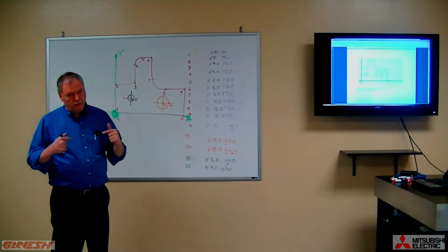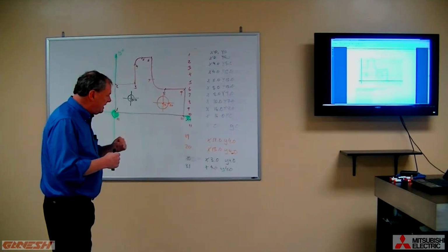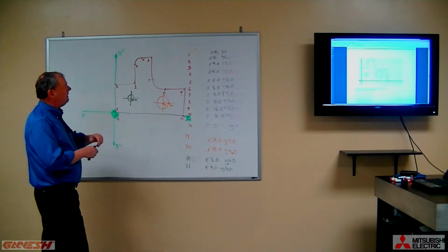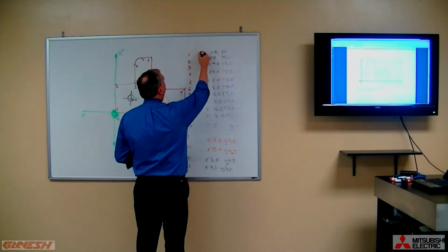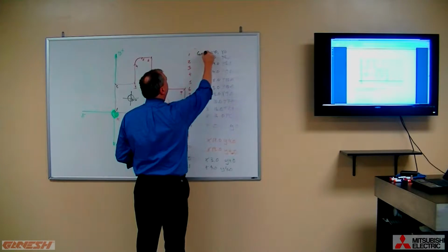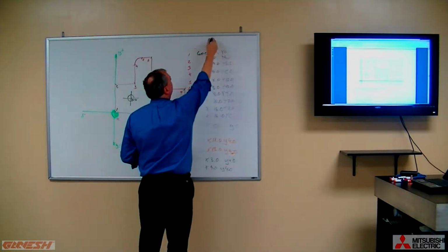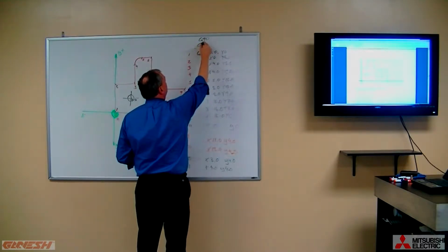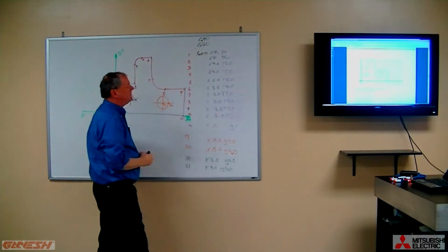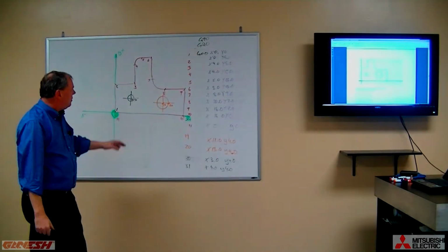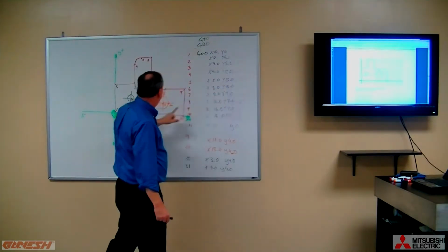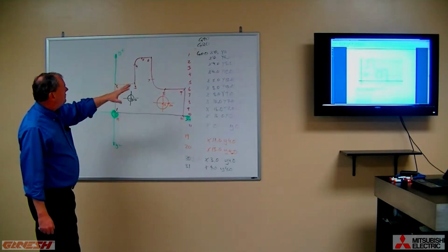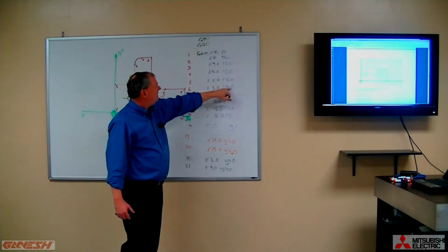Based on what we've talked about so far, I imagine you would want to make our first move a rapid move to x0, y0. So we'll go G00 here, and there's our first move. And then we'll include the G90 and the G20 as well, remembering that G90 says all these coordinates are based on a common datum point, and G20 says all these values are inches.